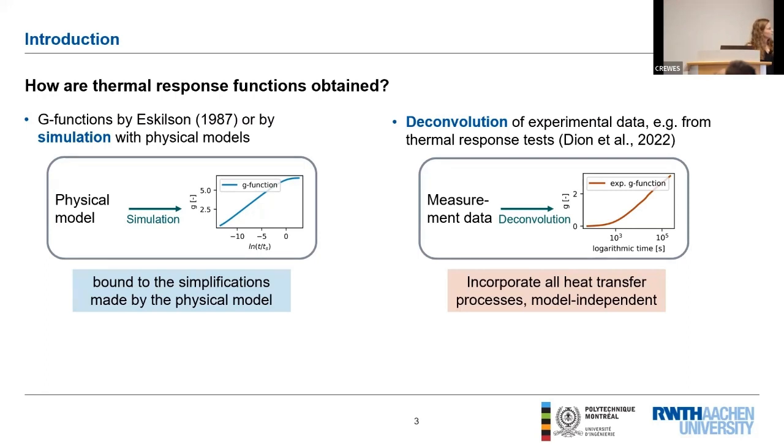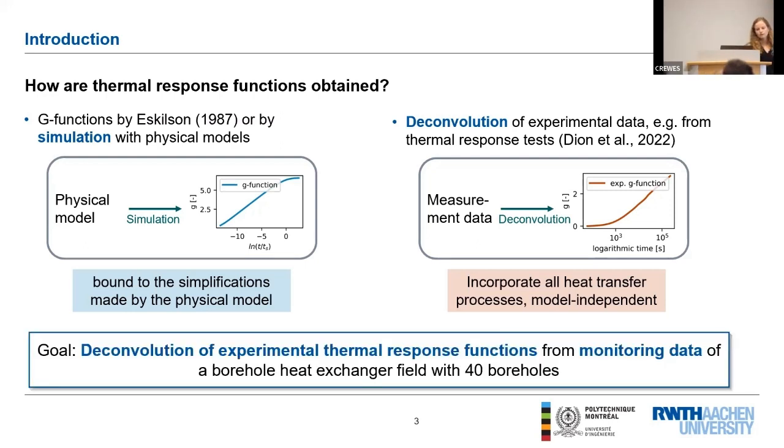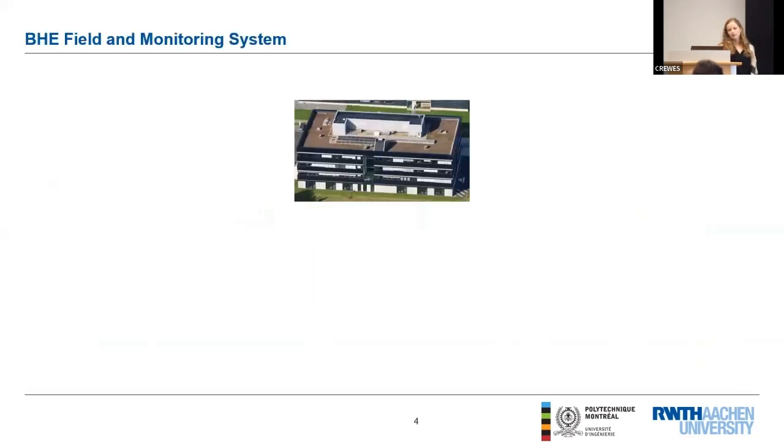But since this deconvolution part is very new, it has so far only been applied to data from thermal response tests and only to data of several days. So what I want to present today is an application of this deconvolution algorithm to monitoring data of a borehole heat exchanger field with 40 boreholes and for a duration of 30 days, so 1 month. And for this, I first want to present a borehole heat exchanger field where I applied this algorithm to.